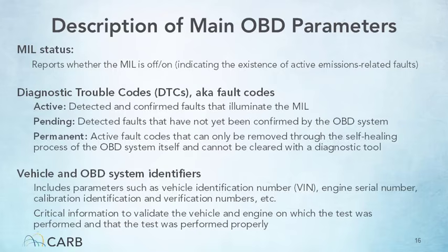The collected data reports whether the three different types of DTCs, active, pending, or permanent, were present at the time of testing. The MIL is illuminated when active DTCs are present and designate an emissions-related issue. Pending DTCs are potential faults that have not completed the necessary confirmative drive cycles to determine a potential emissions-related issue as an active fault. Pending DTCs do not impact a pass or fail determination relative to the OBD emissions compliance test, but provide helpful information on potential future issues.